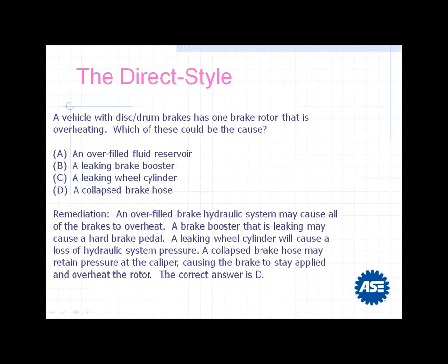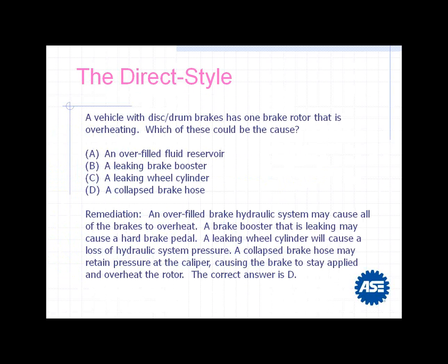Now what I want to do is look at this question for content, okay? I want to look for that key information in the setup of the question, okay? The vehicle has disc drum brakes, okay? It has disc drum brakes, key information. One brake rotor is affected, okay? I've got a single wheel problem and it's overheating, okay? So now that I've looked at that, I look at my options and I've got overfilled fluid reservoir, leaking brake booster, leaking wheel cylinder, or collapsed brake hose.